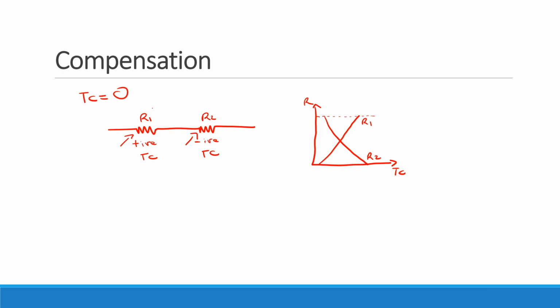So the one with the positive, this might be the N plus poly. This might be, actually, I think that's the P. Yeah, no, that's right. I think this is actually the P plus, and that's the N plus. Right? But it's two physically different things. So when I do the doping of the P, that's completely separate from when I do the doping of the N. So if something is slightly different there, my whole compensation scheme basically breaks down.